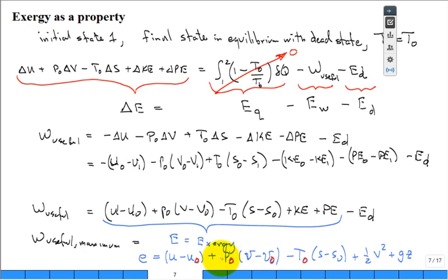Well, this is how you evaluate the property. Let's get to the derivation after we talk about it a little bit. So if something comes in where it's hot and high temperature, it has a u greater than if it's at 25 C and 1 atm. That's the value of the internal energy of the steam, refrigerant, whatever substance I have, at the dead state conditions, at that known temperature and pressure, versus at the current temperature and pressure.